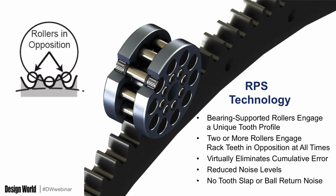The RPS technology is unique. You can see from the cutaway that we have two or more low coefficient of friction, low inertia rollers that are always engaged via a preloaded system. The actual rollers themselves are in opposition. And when the rollers are in opposition to each other, when they are engaged with the gear, you are eliminating backlash. So you're eliminating cumulative error, and you have quiet and smooth motion.